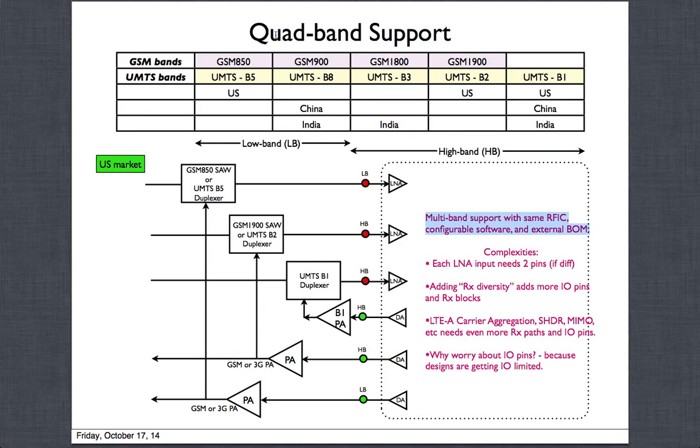So here in this case, as we were talking about quad band support, by doing something like this where the RFIC transceiver is common, and just by changing out the external components, you are able to do quad band GSM support as well as quad band UMTS support, in most of the countries.